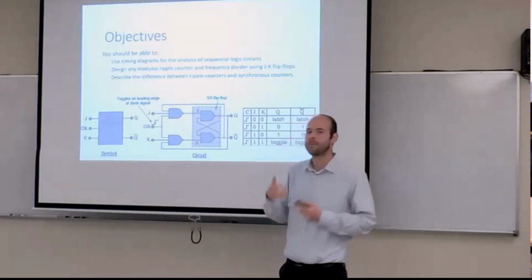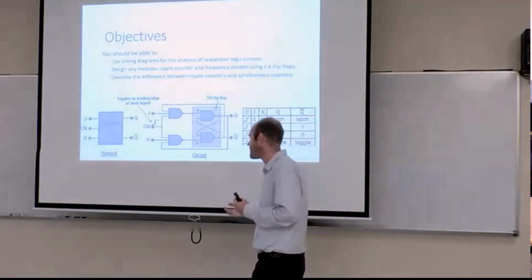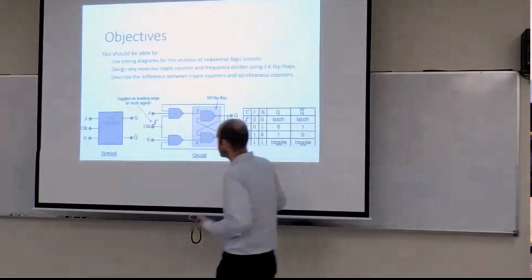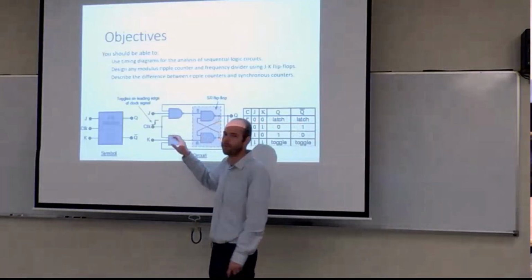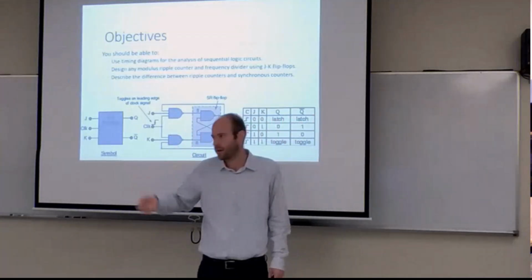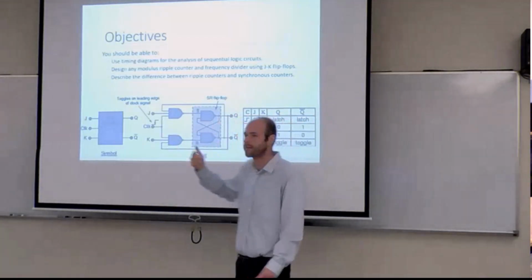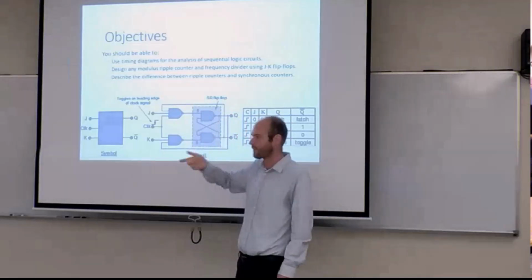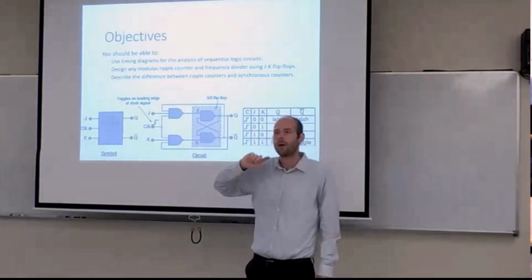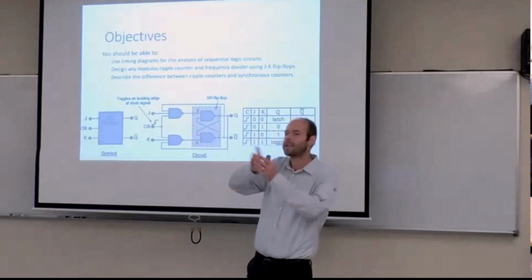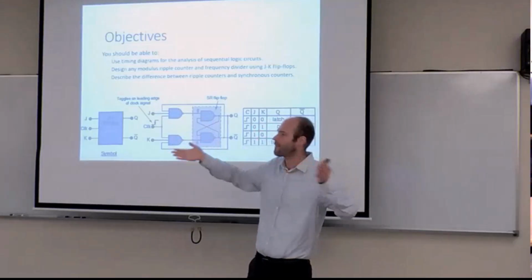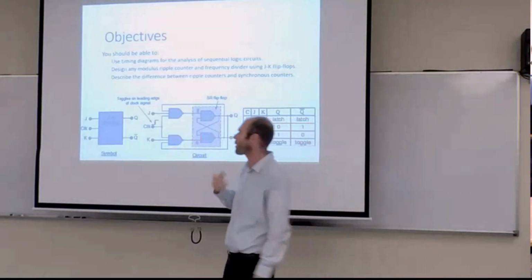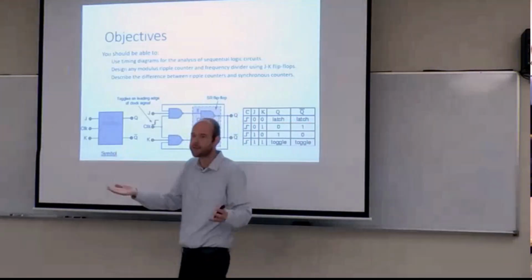We added some enable gate functionality and then copied the circuit twice, separated by an inverter to build out this JK flip-flop that was edge triggered. And that key point gives us as close as possible to the moment in time at which an action is going to occur. So rather than having an unknown activity that's going on whenever the enable bit is high, we now have a specific edge so we can work with exact timing, which is helpful in our system design.